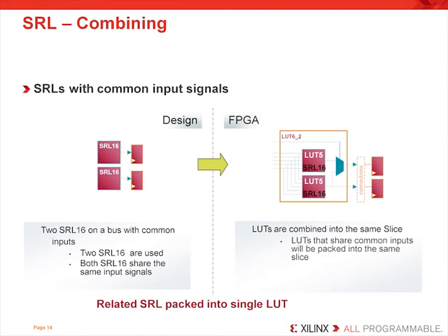Just like we saw in the previous example, likewise here, the implementation tools will automatically try to group the shift register LUTs, remember that's the lookup table reprogrammed as a shift register, and it will group them into the same slice when they share the same input signals.